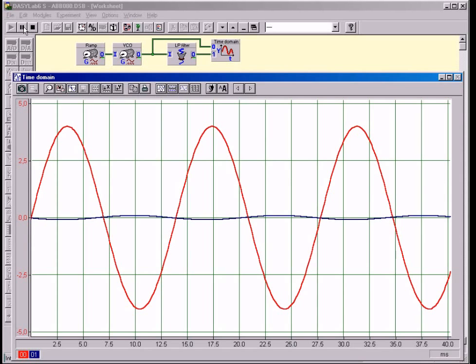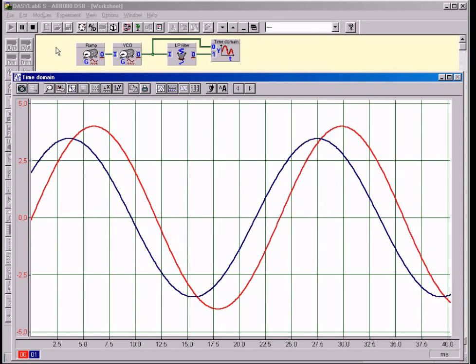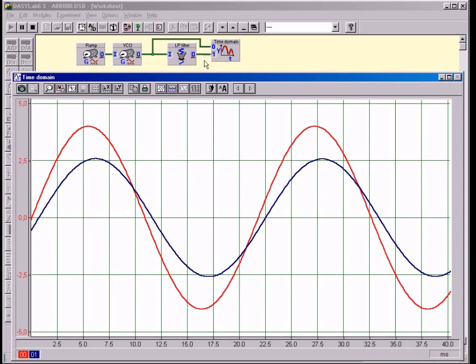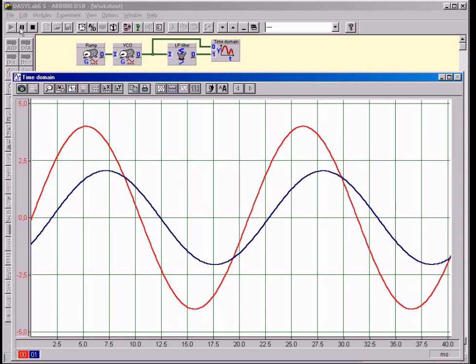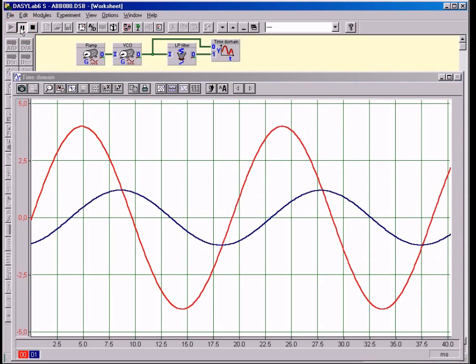The following equipment is necessary: a sine generator and a 2-channel oscilloscope. The properties in the time and frequency domain are to be established by comparing the input and output voltages. Then both signals should be represented simultaneously on the screen.